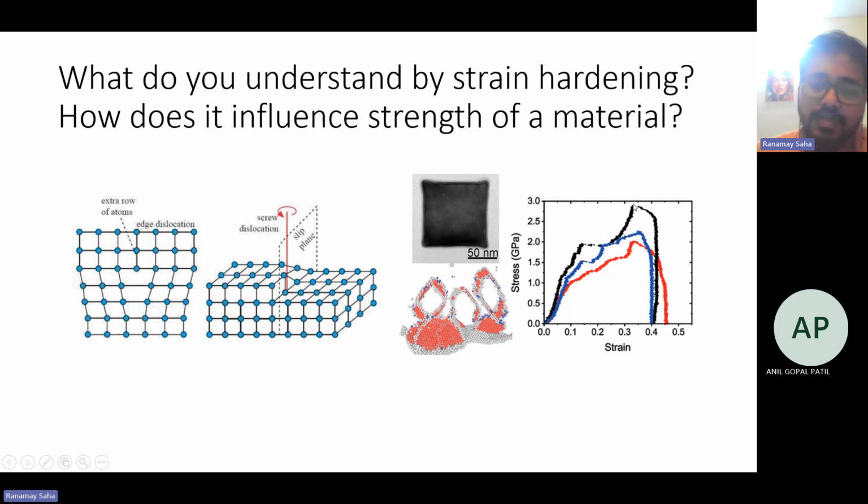So the amount of stress the material can hold is more than the amount of strain or deformation that is actually visible after the yield point, after the material has already yielded. This comes out of the defects present, and this is called strain hardening. The material can now withstand more stress, and we can say the material gets strengthened out of the strain hardening process.